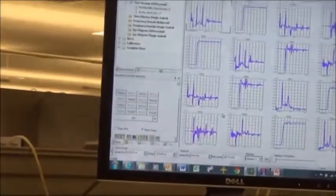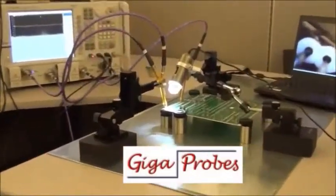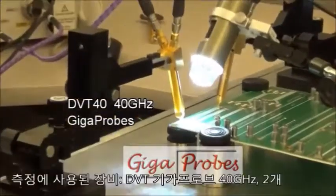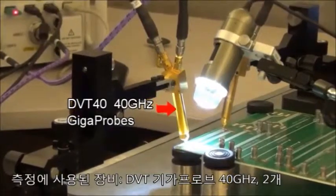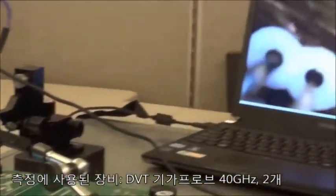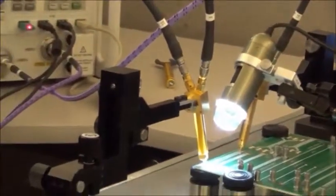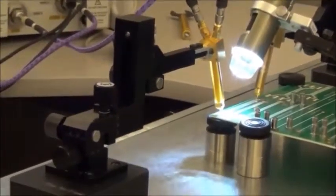software. On the probe setup, we have a very nice, easy to set up system from Gigaprobes. We have two differential probes working up to 40 gigahertz with a small camera system and magnetic bases, and you can see how we get coplanar probe placement on a differential PCB trace with our system here.